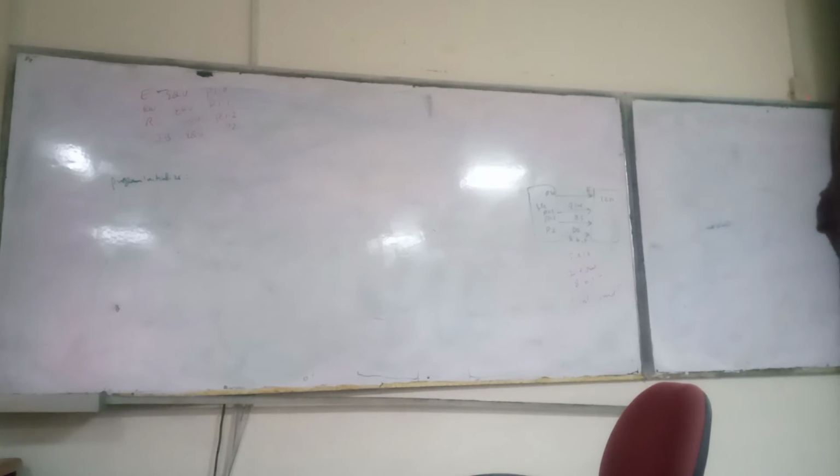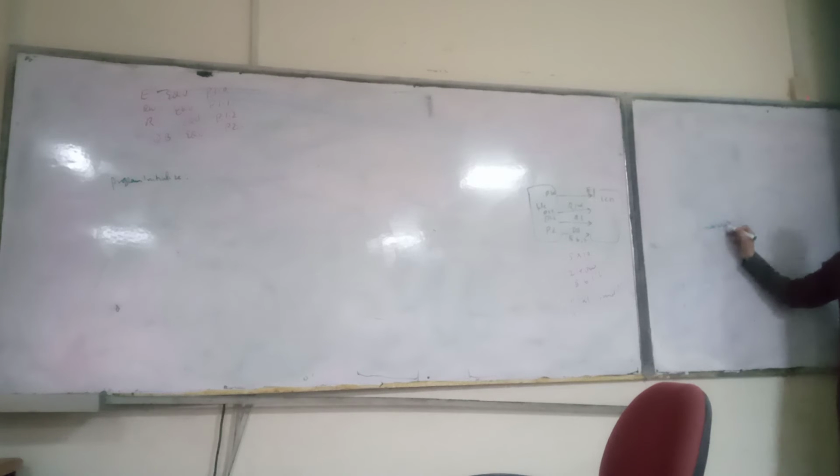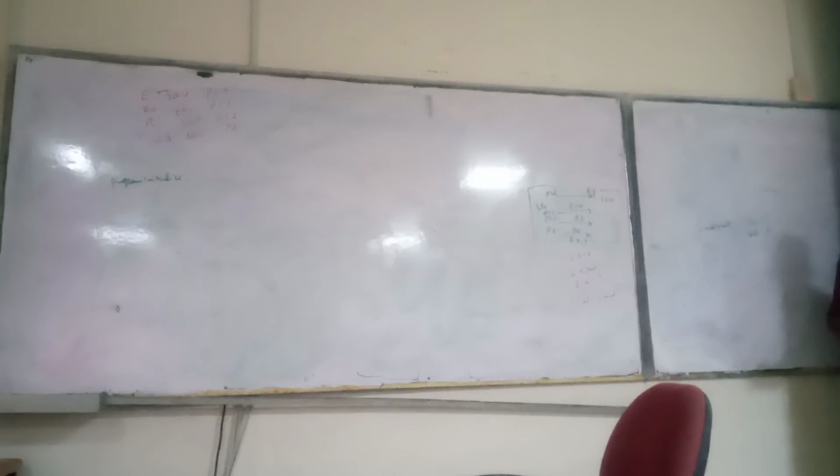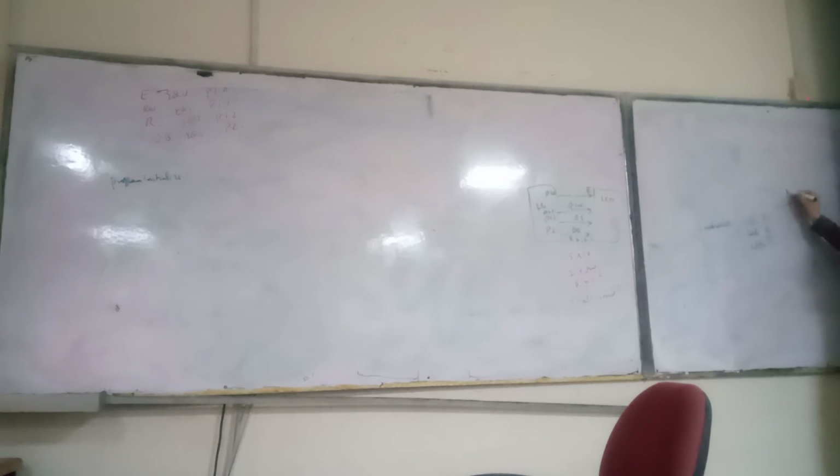By generating a high on a pin of the microprocessor and connecting it to E. We want to generate it by calling a routine, enable LCD. So can we write it like this? Clear E, then set E, then clear E. A pulse will be generated. Initially it will be 0, then high, 1, and then 0. And then return. When this subroutine is called, the data will be moved.